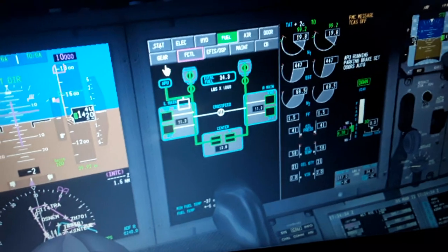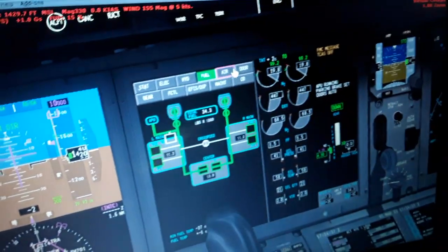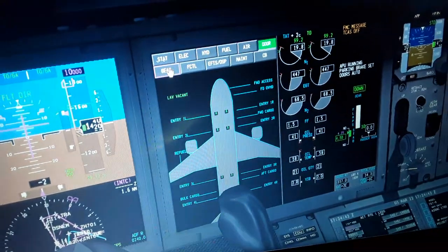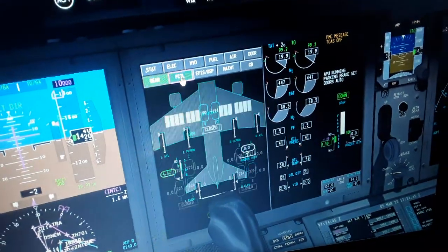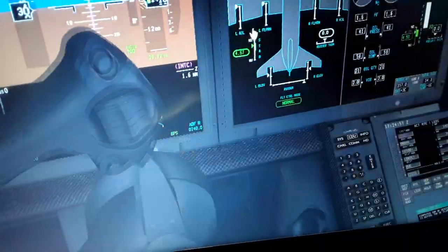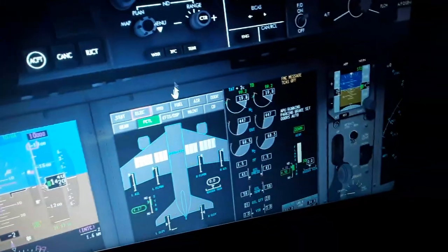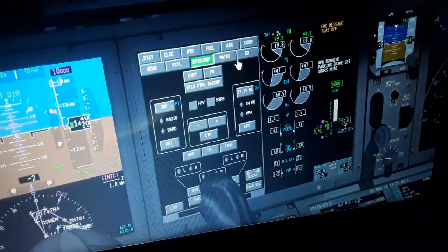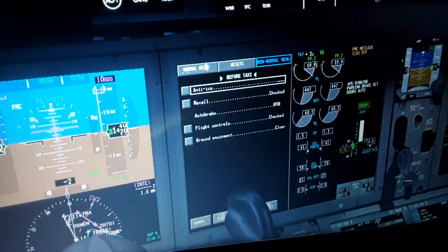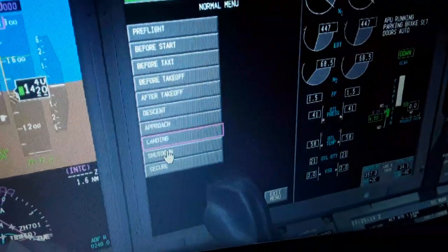So we also have the APU fed from the left wing using the DC motor, pressurization from the left and right engine. The doors are closed, the cabin can be pressurized, the gear, pressure of the tires and flight controls also over here. Moving the flight controls like this, one of the last things we need to know before going to flight. You can see the deflection of the flight controls, the tail also, the rudder pedal phase display over here, maintenance systems, circuit breakers over here. So we have the checklist, what to do before start, after start over here, descent, approach and landing.